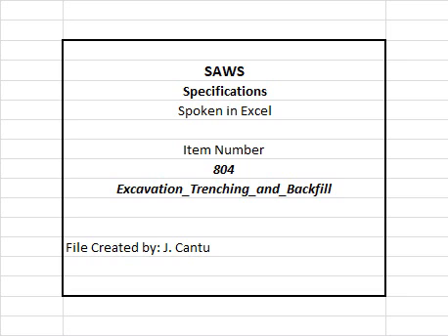2. Submit detailed trench plans, shoring system designs, installation sequences, and flowable fill mix designs. 3. Submit planned typical method of excavation, backfill placement, and compaction including A. Trench widths. B. Procedures for foundation and pipe zone bedding placement, and trench backfill compaction. C. Procedures for assuring compaction against undisturbed soil when pre-manufactured trench safety systems are proposed. D. An excavation plan submittal signed and sealed by a Texas licensed professional engineer shall be submitted for review and acceptance by the SAWS representative, if applicable, prior to the delivery of materials and commencing any portion of proposed construction activities where the planned excavation is 20 feet or greater.